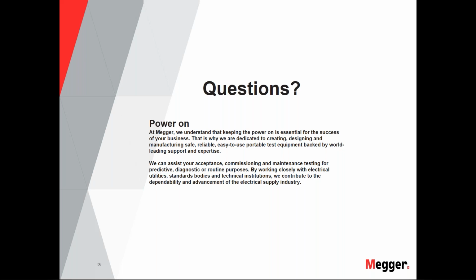However, to answer the question, is it okay to have them coming out of the generator? I would say it's not a matter of okay or not. It's a consequence of physics. Now, the generator step-up transformer, being a delta connected, delta-star connected transformer, takes care of those third harmonics and insulates the generator from the influence of third harmonics coming from the system and insulates the system from the influence of third harmonics going out from the generator.